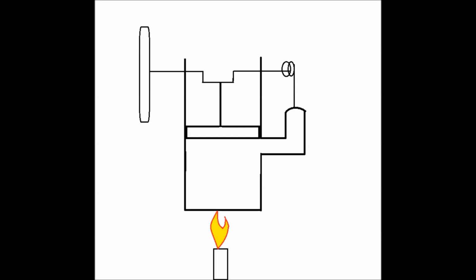And then the air inside the Stirling engine will become hotter and flow upward, and the cold air will flow downward, and that will cause a temperature increase of the air inside the Stirling engine, and then the air will expand. It will push the piston upward, as you can see, and as the piston moves upward, the air will flow into the pipe here, and then the balloon will expand, and the shaft here will pull the crankshaft and rotate it.